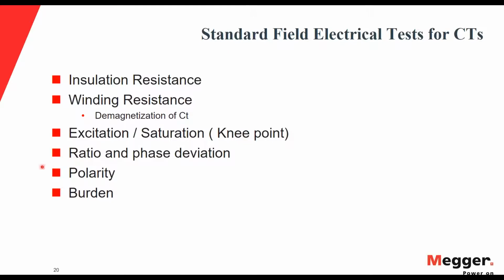And then we have a polarity test. This is very important when you are dealing with differential, distance or directional overcurrent relays, as the polarity will play a huge role there. But also in metering applications, the polarity will define for you, especially in the new smart meters, where they can see exporting or importing